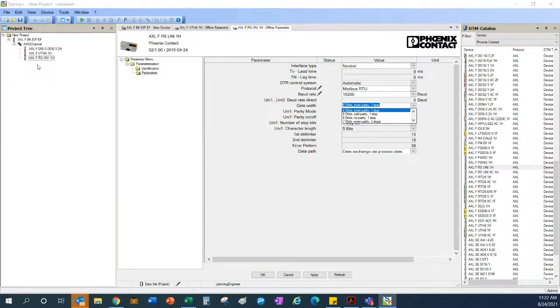So IO-Link is a protocol. Basically, it's a digital channel that can support a communications protocol. So you can use it to set whether the digital input and output or the IO-Link channel is a DI, a DO, or IO-Link. But that's as far as you can go. We actually have a new software tool that's just coming out called IO-Link Conf that does what I just said. Plus, it allows you to use the IODD files associated to the sensor to do the full configuration. So you can do the base configuration here, but the IO-Link Conf, you'll want to use that for the full configuration. That will probably be my next training series that I do, will be on that new IO-Link Conf software, which is on the verge of being released.